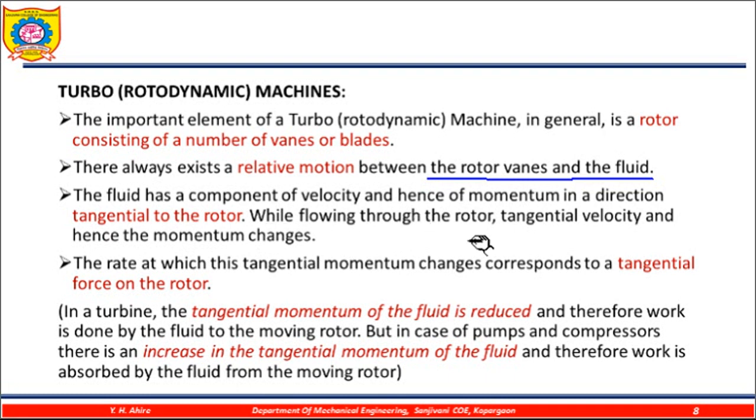While flowing through the rotor, the tangential velocity of the fluid, and hence the momentum of the fluid, changes. The rate at which this tangential momentum changes corresponds to a tangential force on the rotor.